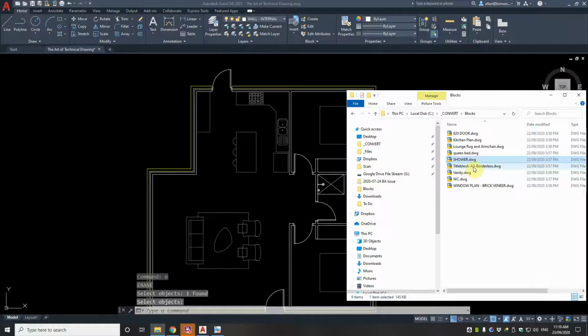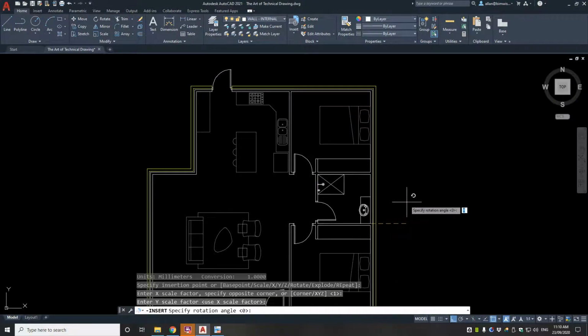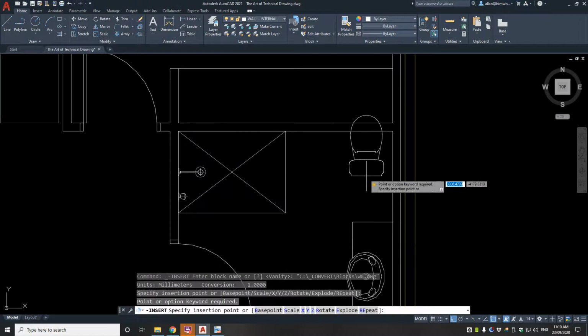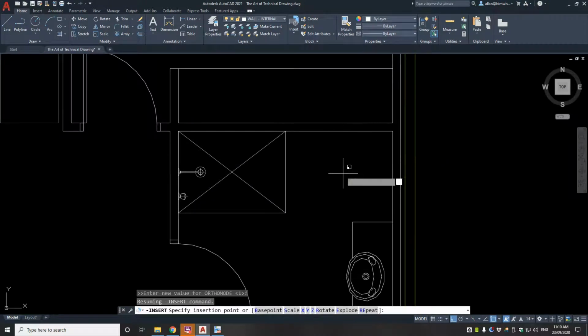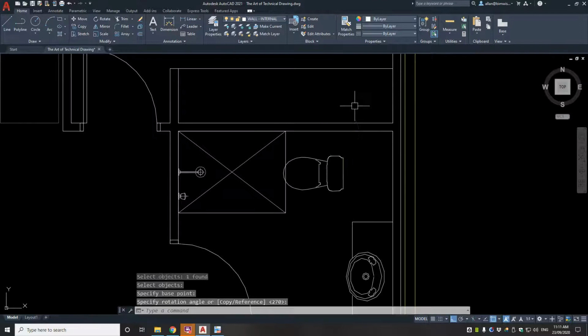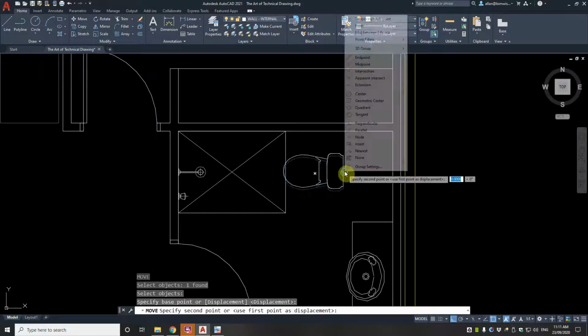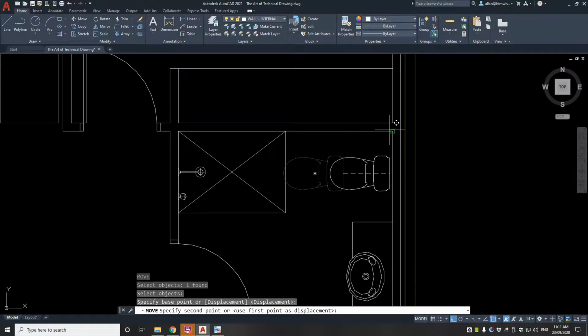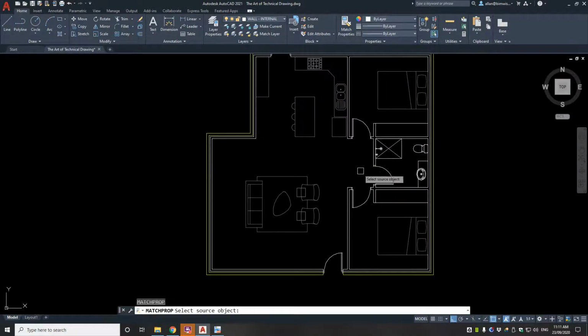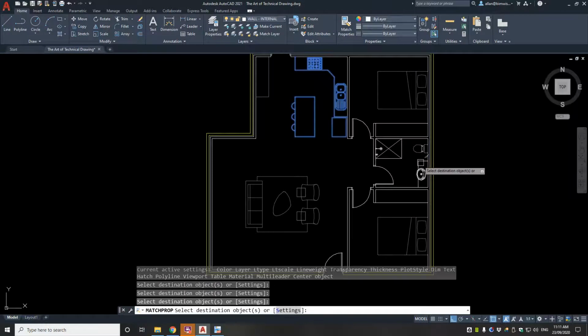Next bit is the border. Well, let's go for the vanity unit. So that's in, and then let's go for the WC, or water closet, which is the toilet. So rotate that 90, move it from there to that point. Now I normally do toilets 450 mils off the wall. That seems to always work, so let's match all that up.